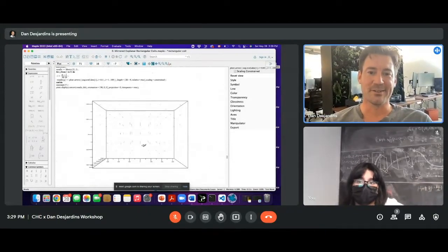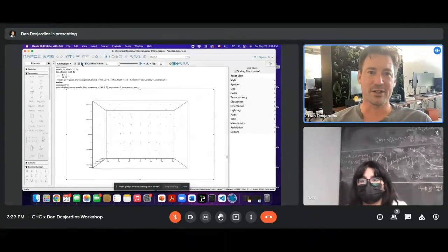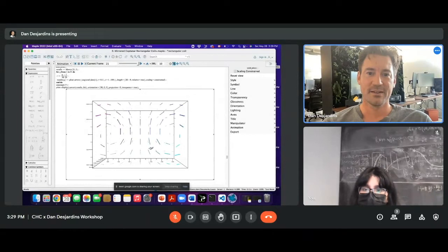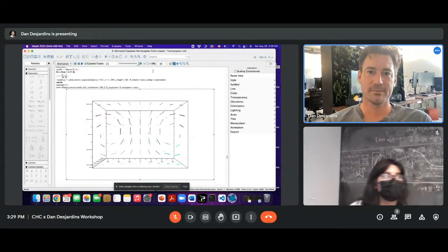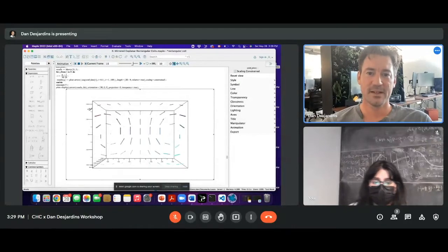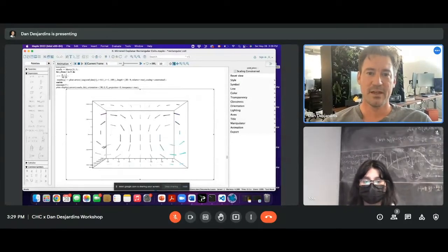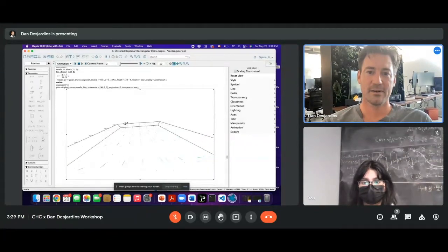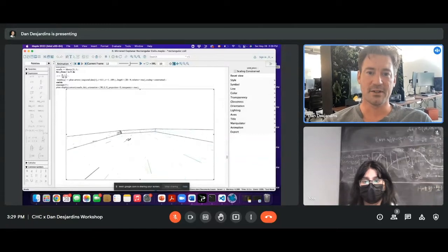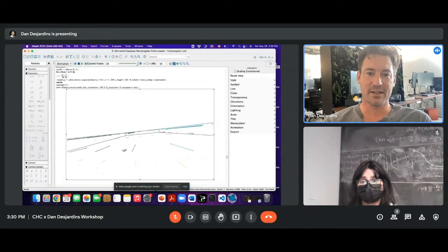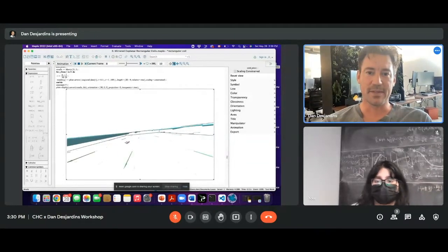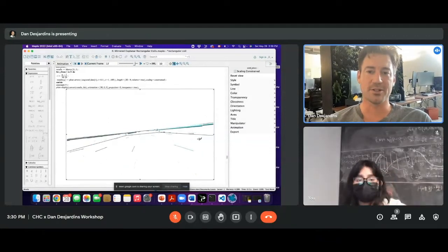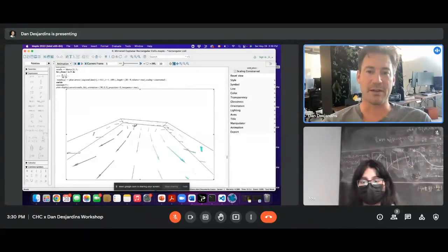And now here's the most awesome part of it all. This is actually a 3D animation. Let me make it go in a loop. These are the currents being induced in the coil. And you can see that they're strong at the surface, and as you get deeper down, they get weaker. And you can see that they're even lagging, right? See how they're slightly behind, so there's that underdamped oscillation, if you will. So it's just cool. All this comes from all that math.